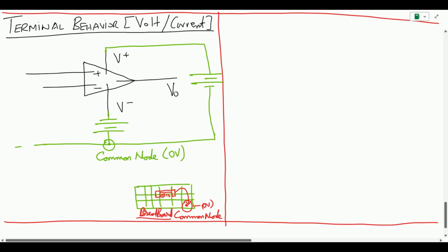Okay, so now let us see what the voltages and currents are when interacting with this operational amplifier. For the voltages, let us call the positive side Vp, the inverting side Vn, and the output Vout. This is the negative VCC, and this is the positive VCC entering into the op amp. Since our ground is common, we can say there is a voltage rise for Vp, a voltage rise for Vn, and a voltage rise for the output voltage, and the supply of plus VCC and negative VCC remains.